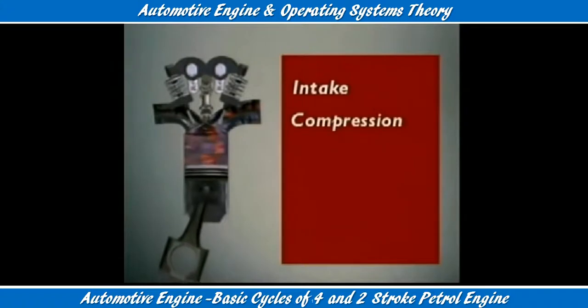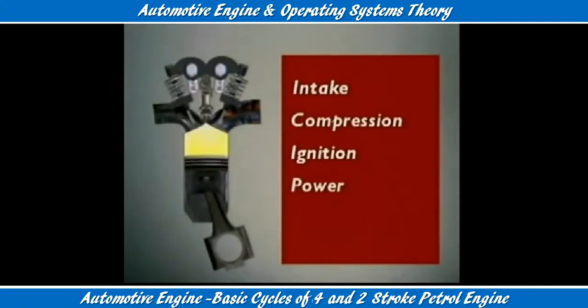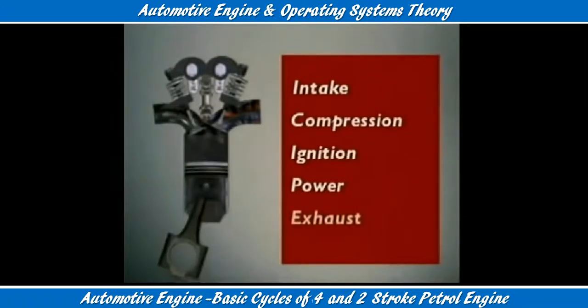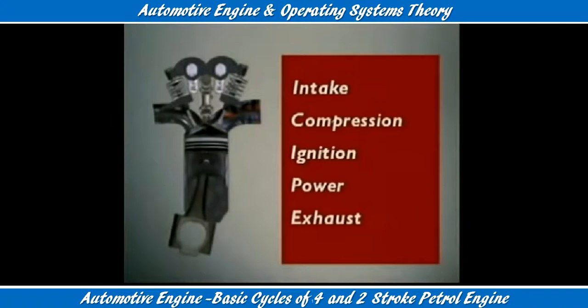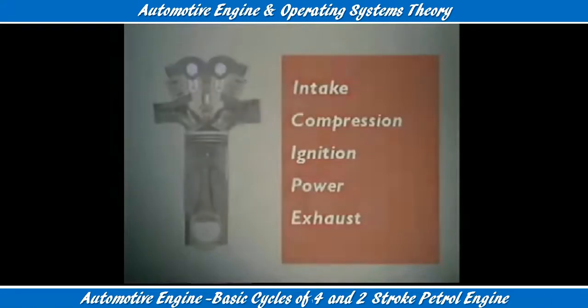Compression squeezes the air-fuel mixture into a smaller and smaller volume. Ignition, the mixture under pressure is burned. Power, burning expanding gases push the piston down, creating a power stroke that turns the crankshaft. Exhaust, the piston moves upward, forcing burned gases from the chamber. All 5 events occur in this order in each of the engine's cylinders.